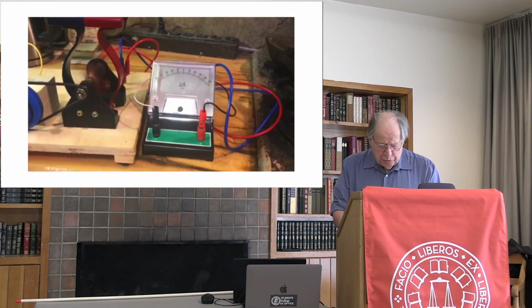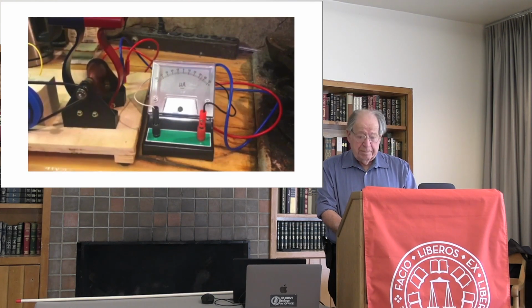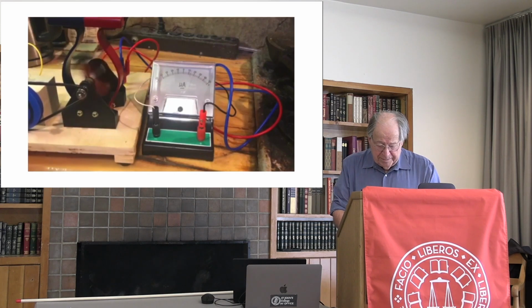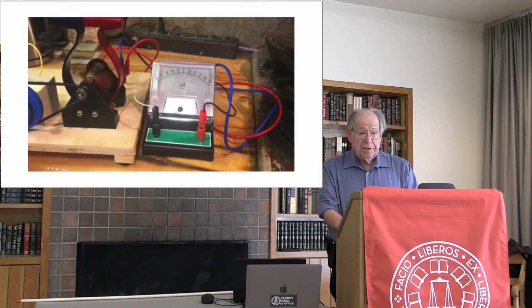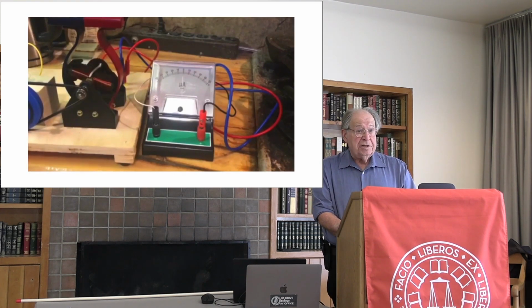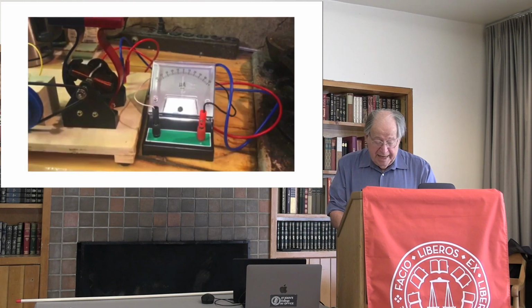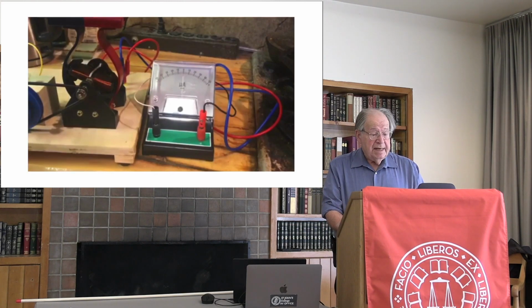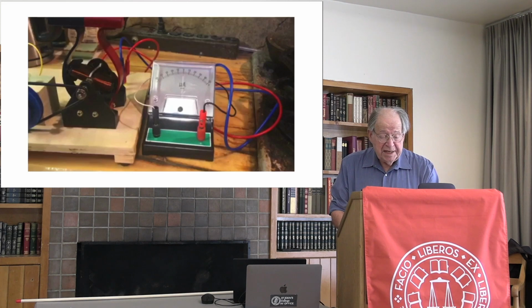But what does this relatively steady reading represent? At these high speeds, the meter's needle cannot keep up with the current's rapid excursions between 0 and peak value. The meter indicates only the average value of the pulsating current.